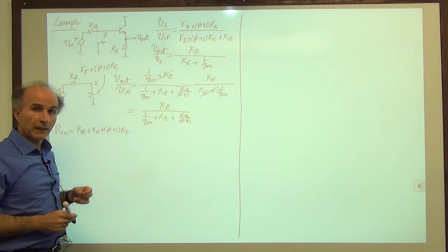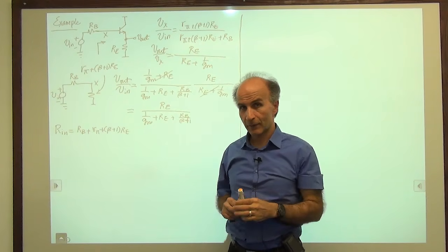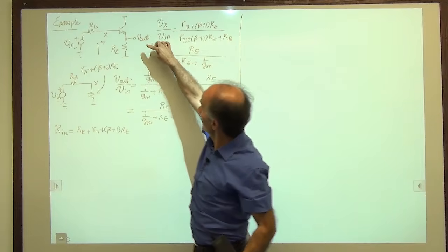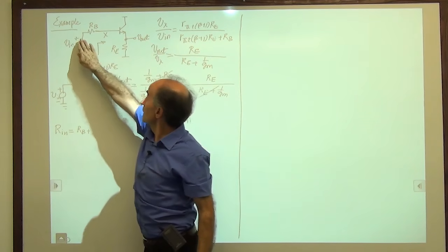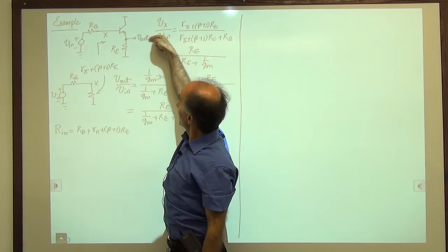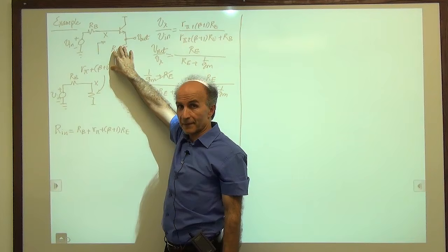Okay. Now let's go on to R out. R out is the output resistance of the circuit. Meaning I sit here, I set all independent sources to 0. This is 0, that's 0. I apply a Vx here, measure Ix, and that ratio is the output resistance.